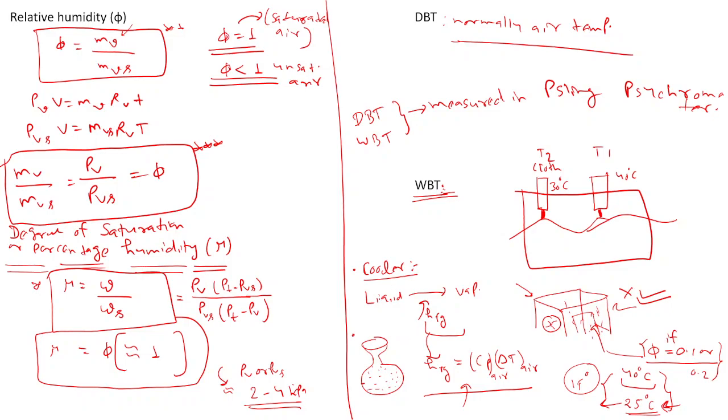So the first significance is that whatever minimum temperature we can get in this desert cooler is the wet bulb temperature. Whatever the temperature of the water in the earthen pot in summer, the minimum temperature possible is the wet bulb temperature. Is it clear? Yes, sir. And the last one is the cooling tower, which you would have studied in your syllabus, right? Yes, sir. There also the same thing happens. In a cooling tower, maximum cooling is possible only till the wet bulb temperature of air.